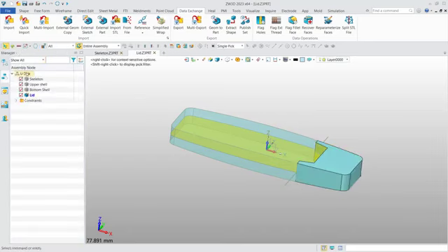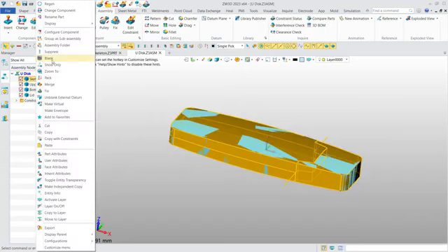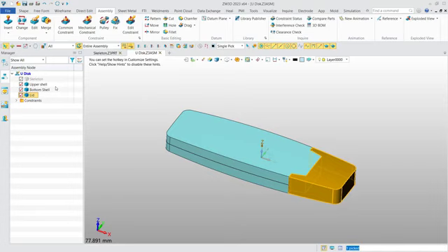Okay. Now we can activate the top assembly and update it. And now you can see we actually have the upper shell, bottom shell, and the lid. And then now actually we can hide the skeleton. Okay, then we get the 3 components, and then we can activate them and do the detailed design.